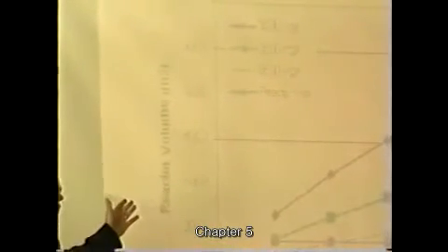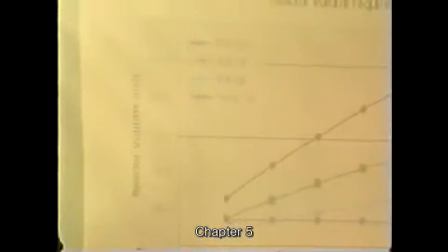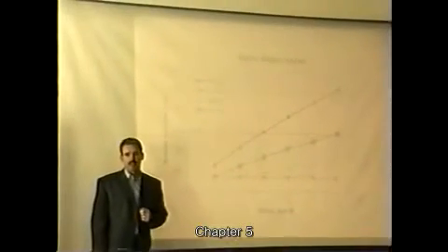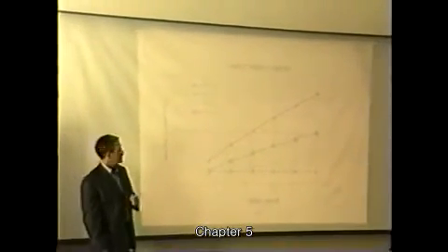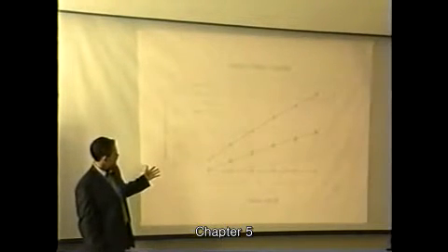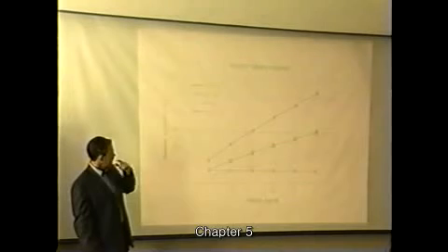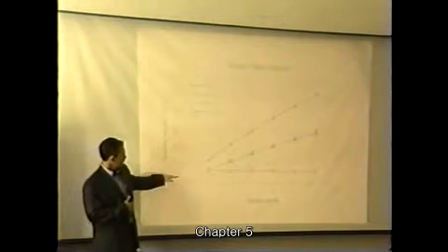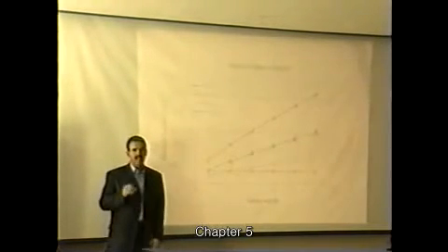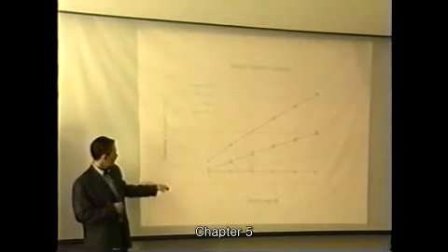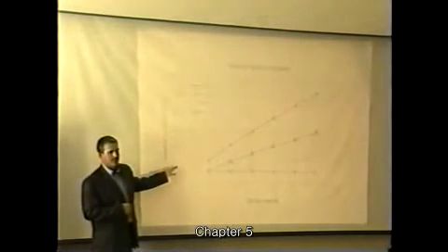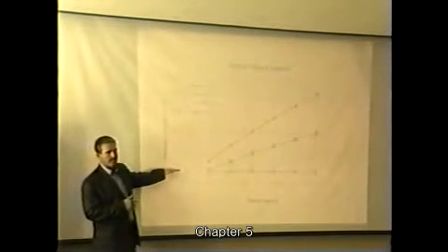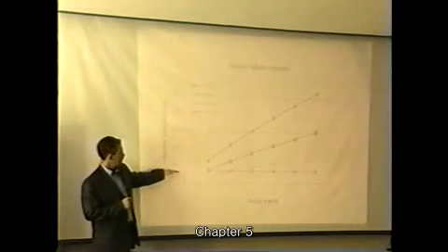So you can draw up these curves, and this was done for a reactor that is supposed to treat 20 megaliters a day, which is more than 20,000 tons, and then operated at certain mixed liquor concentrations. The straight line is the actual basin size. It's less than 2,000 cubic meters, less than 2 megaliters. So the residence time in this basin is approximately 2 hours.